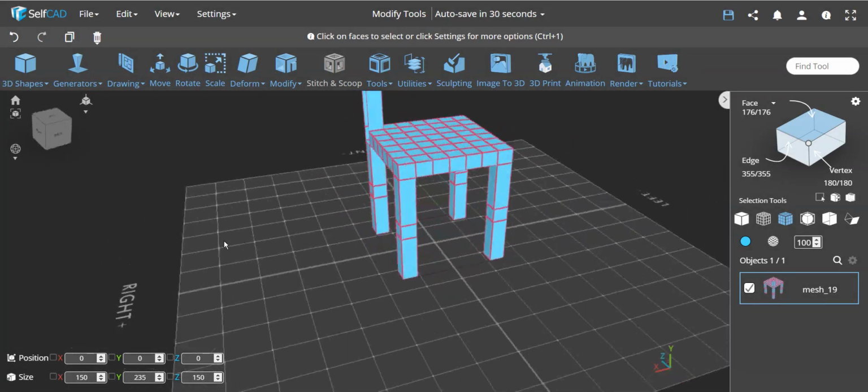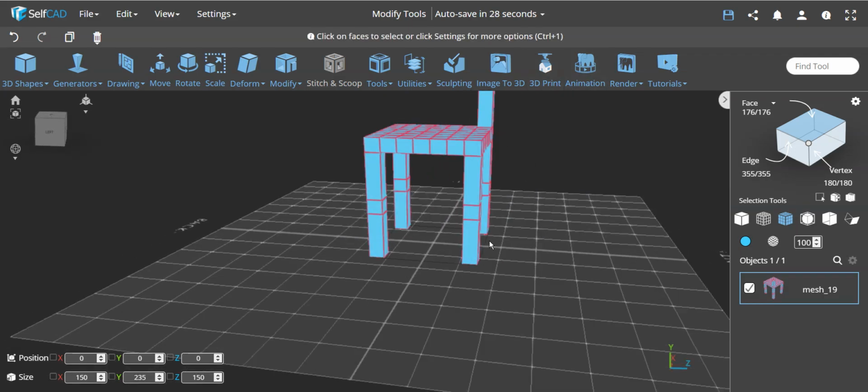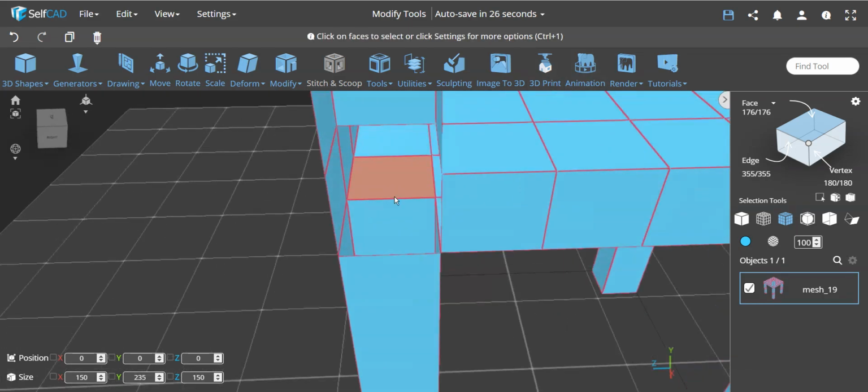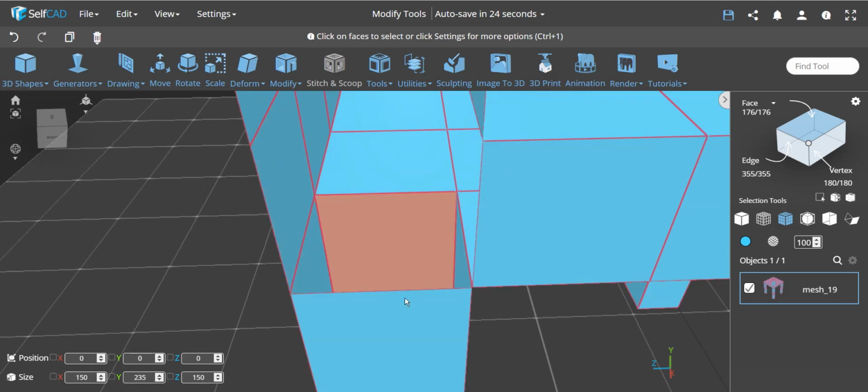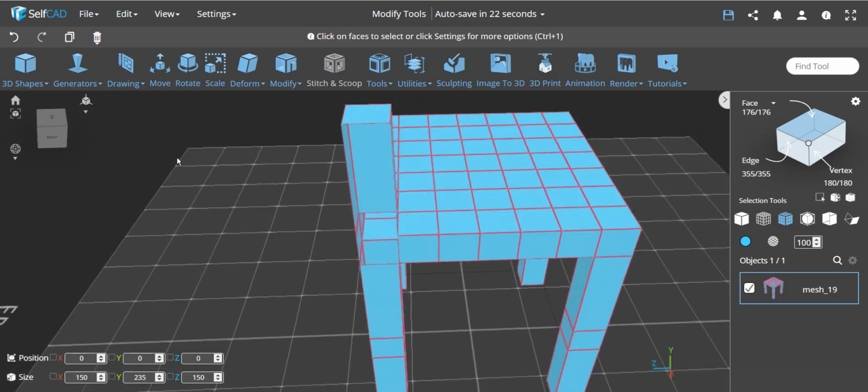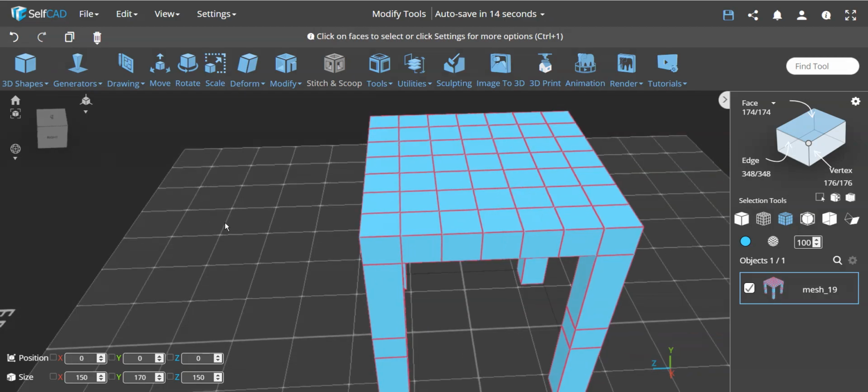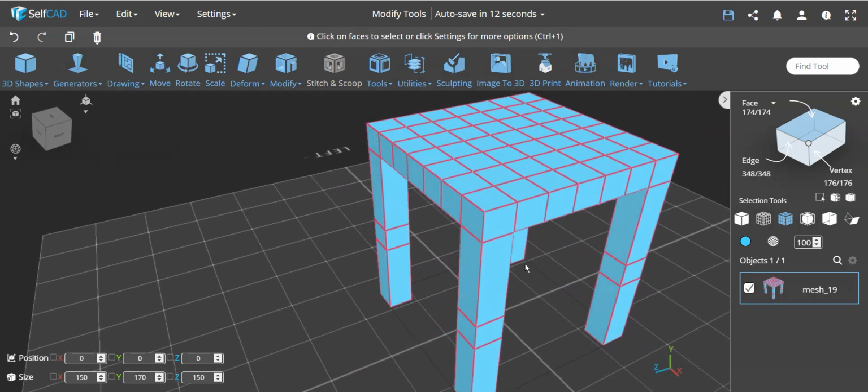You can see the back face you see over here, but the inside face actually is removed. It's hard to see maybe, but this face here was removed. You can see there's a hole over here. It's completely removed. And this is actually very important from the concept of keeping objects manifold, or watertight, whatever name you go by. Basically that means that the object has to be an uninterrupted volume.